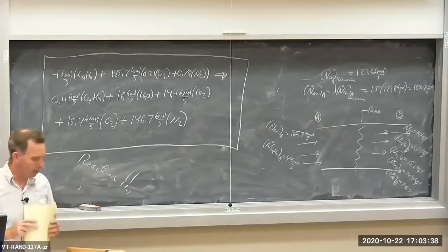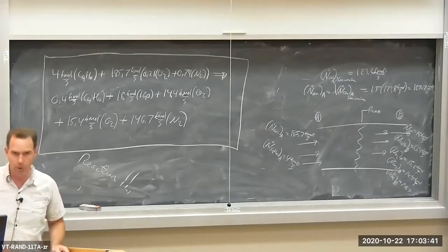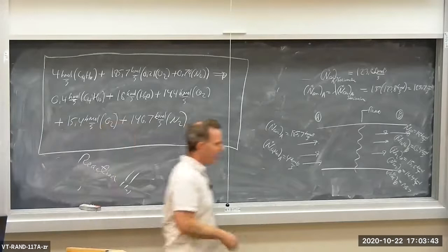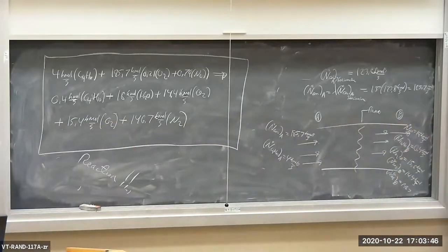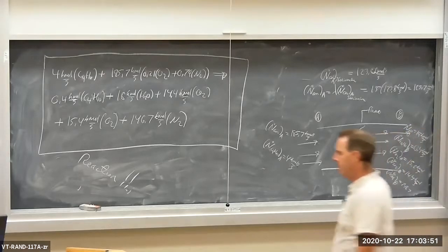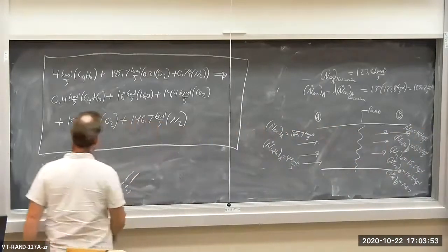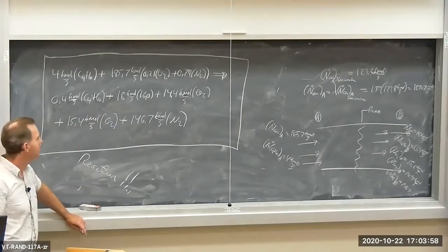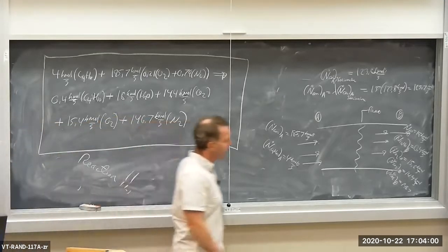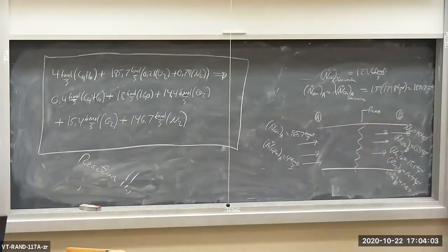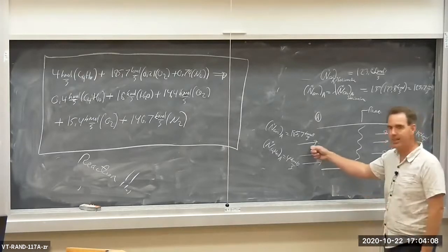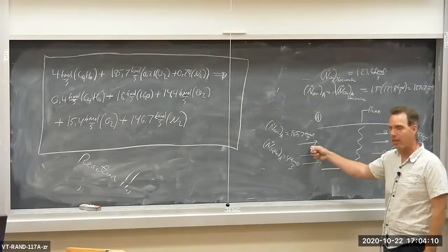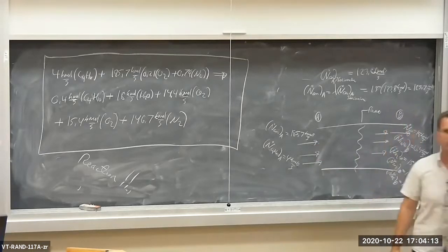It's a pretty good start on chemical reactions. What we're going to do next time is take a situation like this involving some fuel, burned with air, and apply the energy balance to determine the heat release. So this flame here is releasing a lot of heat. So we're going to apply the energy balance to our reacting systems. What's different about what we've seen up to this point is the inlet composition chemically is different than the outlet composition chemically.